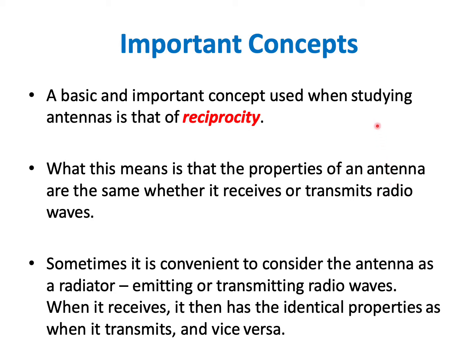The first thing to note is this concept of reciprocity. Reciprocity means that an antenna has the same properties whether it's receiving or transmitting radio waves. So for measuring how an antenna performs, instead of having the antenna receive, you can have the antenna transmit instead and then look at the power it's radiating around it to see how sensitive it would be. But we'll get into that later.